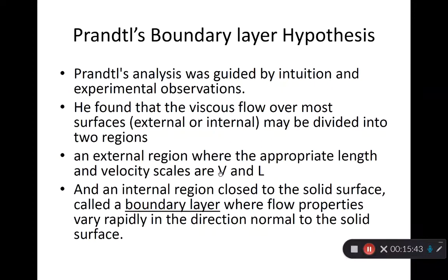And the velocities, if you measure them, are of the same order as the velocity of the free stream. And the length scales over which changes take place are of the order of the chord length of the aerofoil. So things are changing very, very slowly in the outer region, and there's no viscosity.